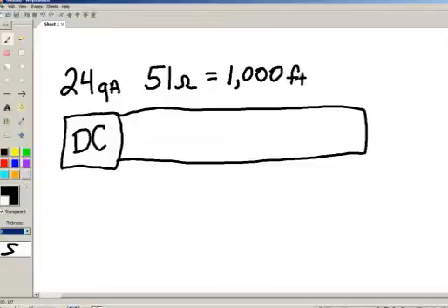Now, an important note on our ohms to distance calculation: a lot of manufacturers, when you are looking at a short, will give you a distance back that you have to cut in half again to get to the location of the short, because the distance they'll provide you back is the overall loop length, right, out and back. Well, that never made sense to us. I mean, we always thought, well, heck, you're looking at a short, you're interested in where the short is, right? So we cut it in half for you. So any distance you receive will be a distance to the short.